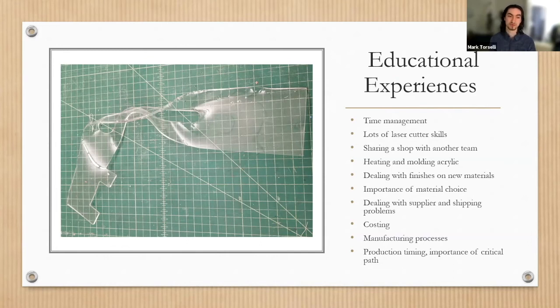We definitely learned the importance of material choice. We couldn't go with the exact materials we wanted to because of constraints besides aesthetics. Like, we wanted to use wood at first, but we just couldn't work with it. The plywood that we were using just wouldn't cut properly on the laser cutter. It would burn too much and mess up the tolerances. So we had to settle for MDF, even though it wasn't the prettiest thing. It was just the most practical choice we had.